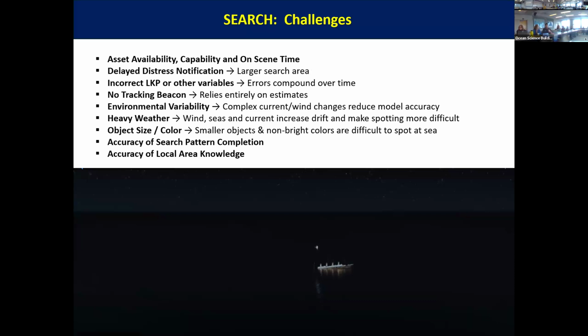I can nose up and get pretty close to, say, a bridge because that bridge is not moving. A buoy on a large scope of chain that could be swinging depending on the currents, I'm going to give that more room with a ship just because I don't know exactly where it is as it's moving. So anything that's tethered and could swing or move is going to prevent me from getting closer to it.